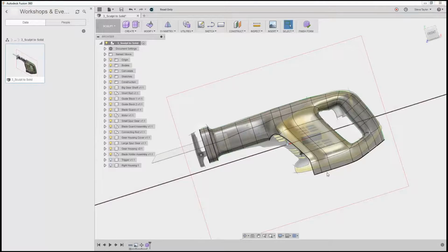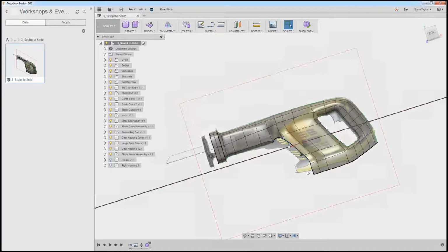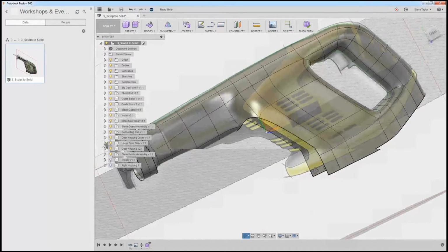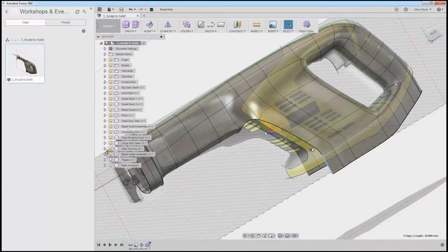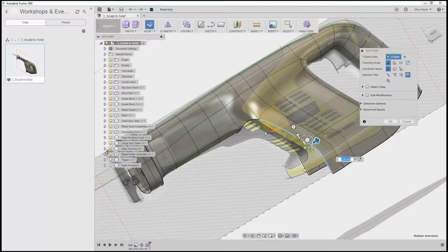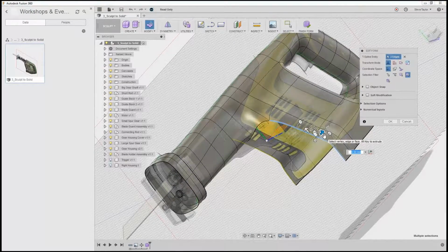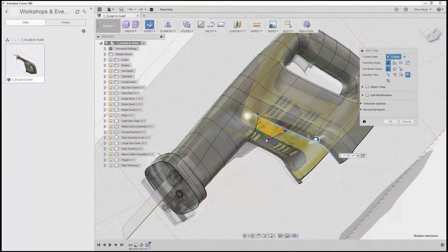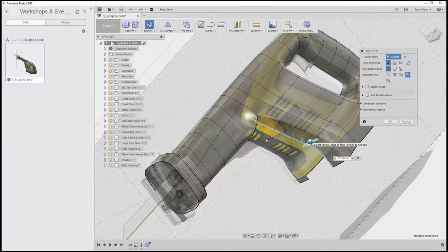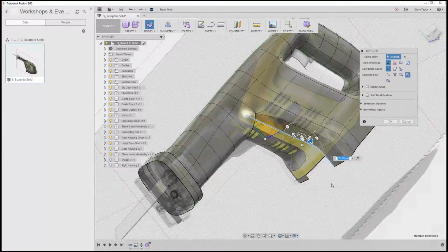So what I'm going to do, I'm going to first of all grab these 3 front edges. So if I, no, that's grabbing too many. So what I want to do is just very quickly go 1, shift select 2, 3. Then using the Alt key, hold on, modify, using the Alt key and the arrow, what I'm going to do is just bring in here, Alt in, and start closing it off in that direction there. So I've now started to grip and bring in.